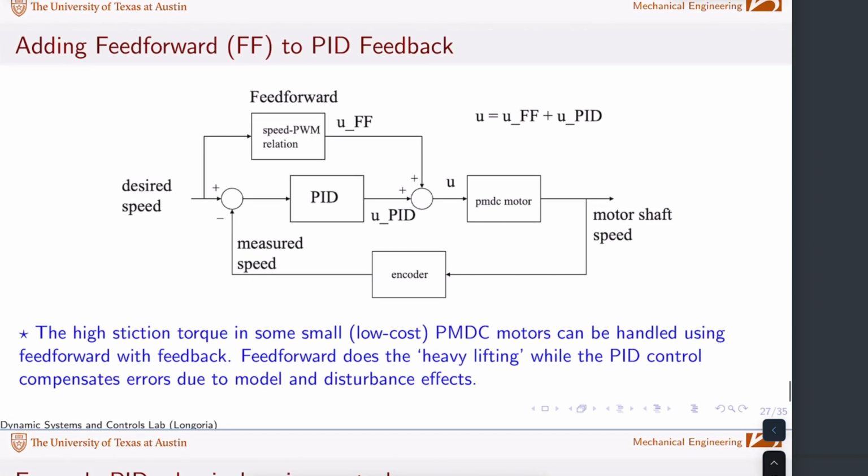All right, so finally, turns out you can add another form of control, so that the total control action could be not only what you base on error, but also, if you know a little bit about your system, you can add a little bit of what we call feed forward. So we could use our open loop control. Turns out this can be very helpful because if this is reasonably good, then this error path has less work to do, if you want to think about it that way. So the total control action is a feed forward part plus the PID, which is an error-based part.